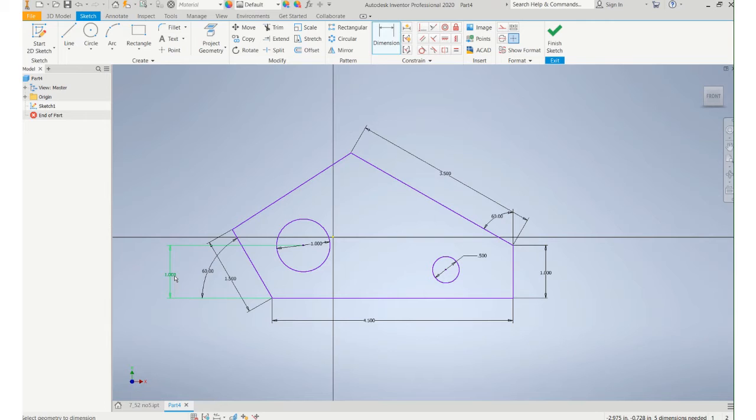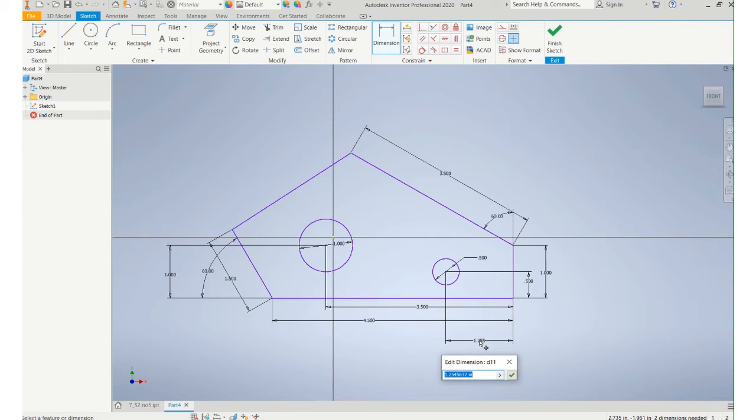Now one thing you'll notice is the dimensions on the sketch don't show up on the drawing sheets. You can actually use poor dimensioning practices in terms of locations of the dimension. I'm just programmed to not do that, but as far as dimensioning on the part and so forth, it's okay. Part of the problem with doing that though is that it really clutters up the drawing, so it's really advantageous to use some decent dimensioning practices when you can.